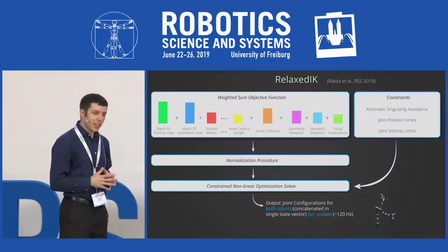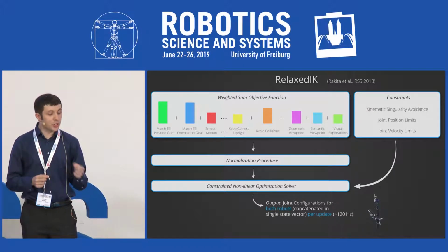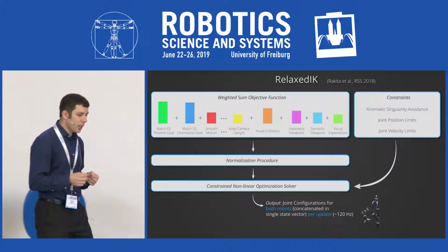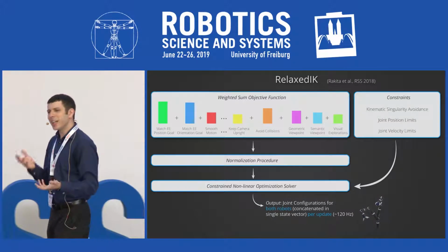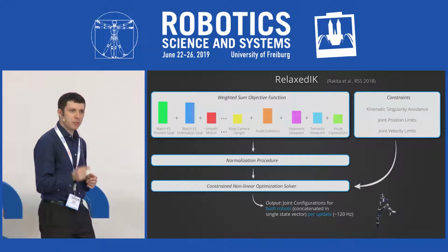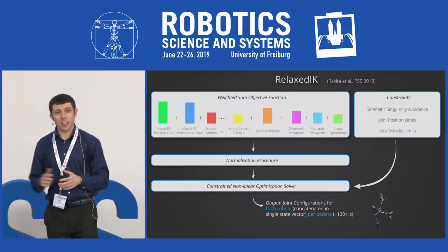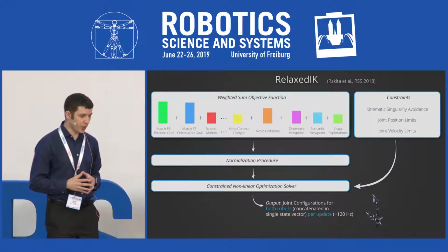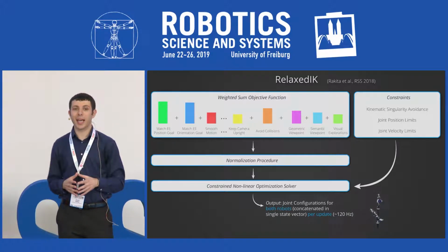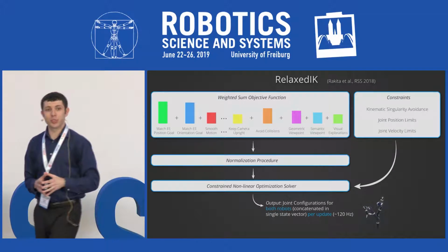We utilize the RelaxIK solver to achieve real-time motion optimization performance in our method. The solver uses a flexible nonlinear optimization formulation to account for motion synthesis problems that dynamically trade off between multiple objectives on the fly, and is able to achieve per-update motions that accurately match end effector pose goals without exhibiting collisions, kinematic singularities, and joint space discontinuities. We incorporate our geometric, semantic, and visual exploration viewpoint adaptation types into the RelaxIK optimization formulation by adding additional terms in our objective function.